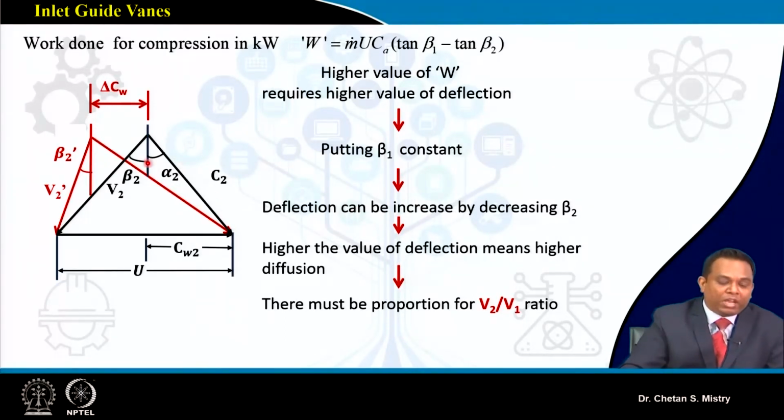So here if you look at, this is my original velocity triangle, in which we have our relative velocity V2 and my blade angle at the exit, or my relative air angle, that is beta 2, at the exit. And as per our understanding from our fundamental equation, we want to reduce our beta 2. So this is the configuration. I am reducing my beta 2.